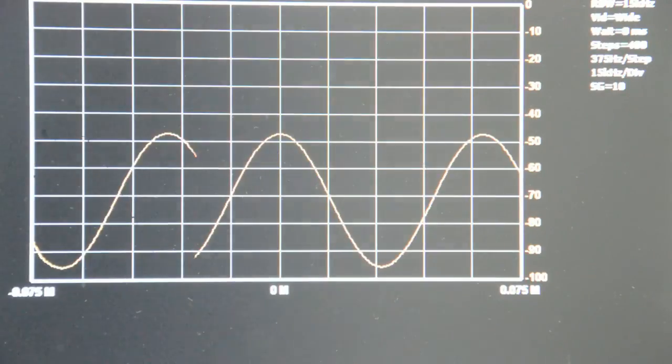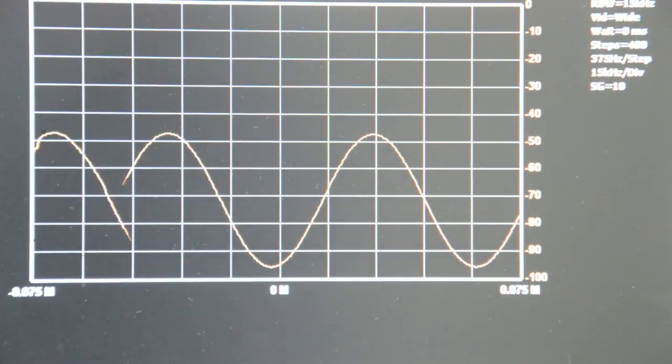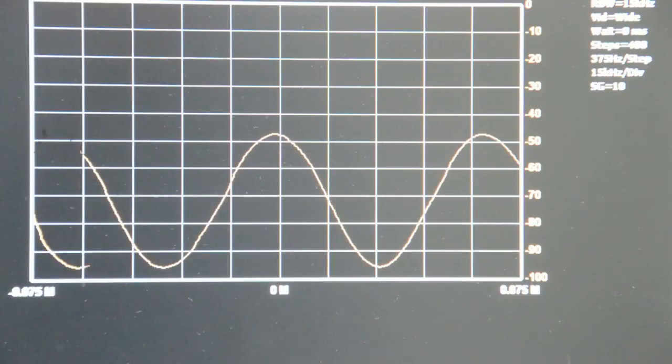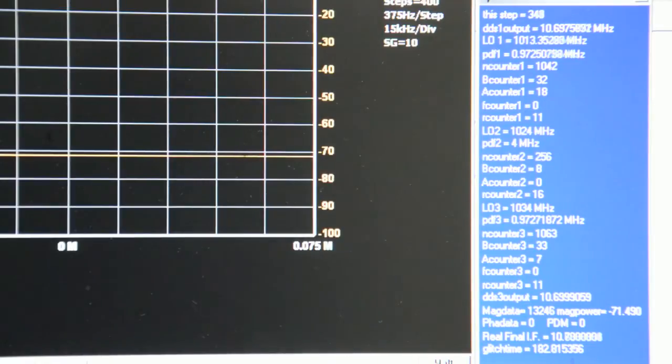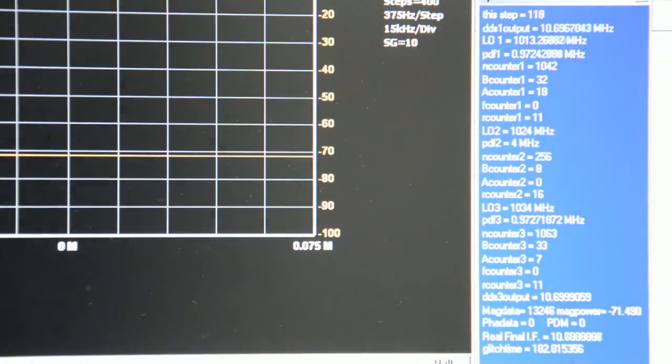And as a last test, I will set the signal generator to DC and check the ripple. Okay, I forgot to mention in the test before, the frequency of the sine wave was 1 Hz, so what you saw on screen was exactly what I fed into the ADC. This was just a way of abusing the spectrum analyzer software to get the data and display it to visually verify that everything is working.